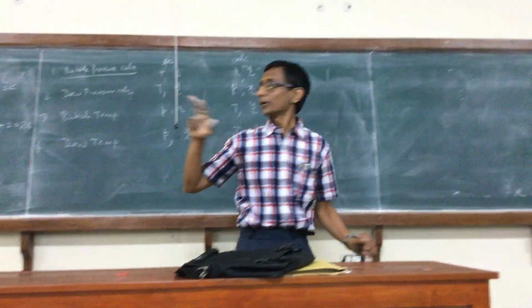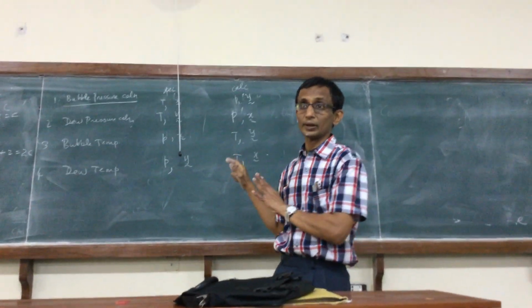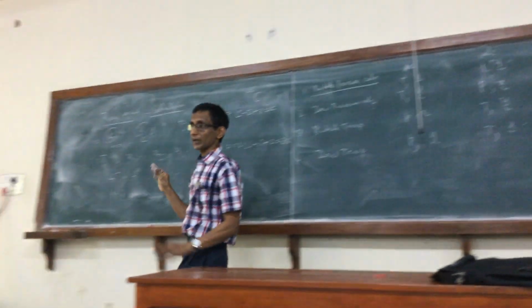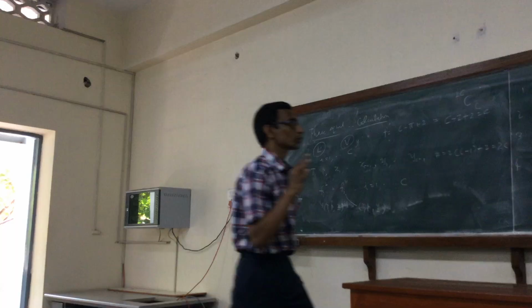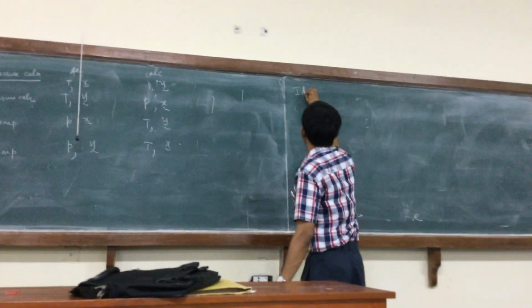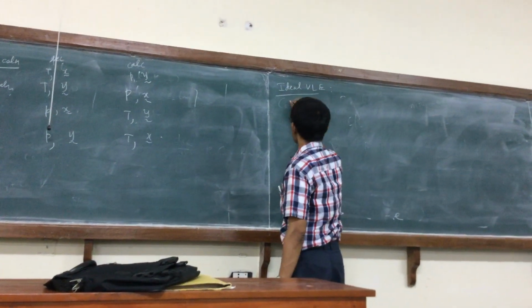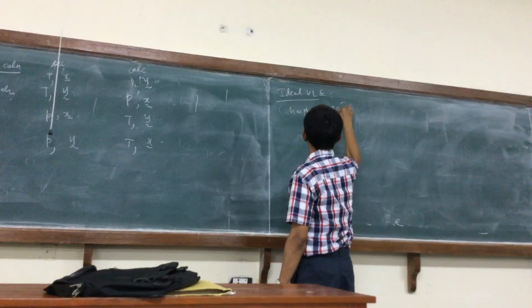Now this is valid without considering any particular model for the fugacity. We have not even considered the number of components. The only thing is vapor liquid, and so it's very general. Now we will take a particular model. The zeroth order model in vapor liquid equilibrium is the ideal vapor liquid equilibrium. In this, the gas phase is treated as an ideal gas mixture.